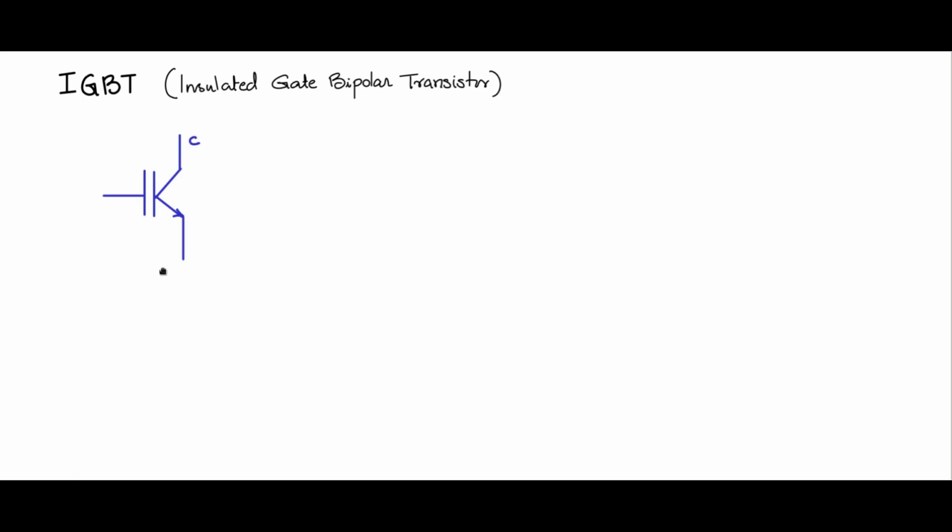You will see that the power side has the symbol which is similar to BJT, and the input side something like the MOSFET. That is because of the insulated gate. The control is voltage controlled, unlike the BJT which is current controlled. Here the IGBT is like the MOSFET, voltage controlled, has gate insulation, and because of that it has a high input impedance.